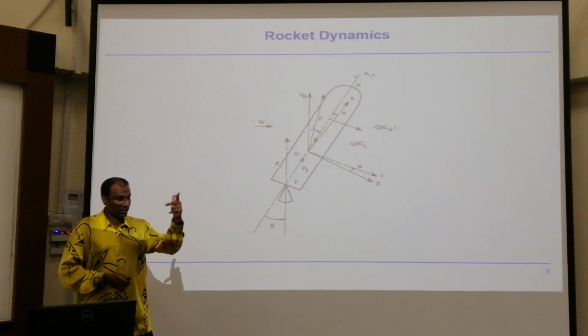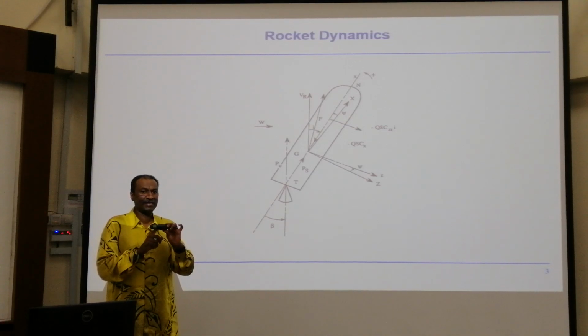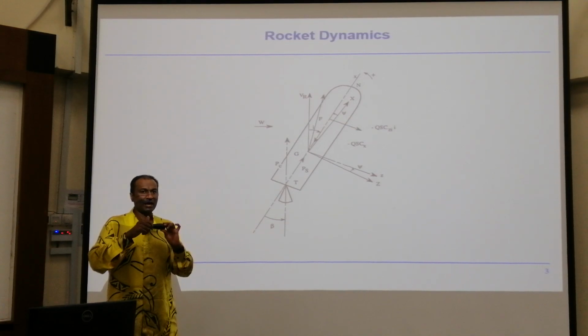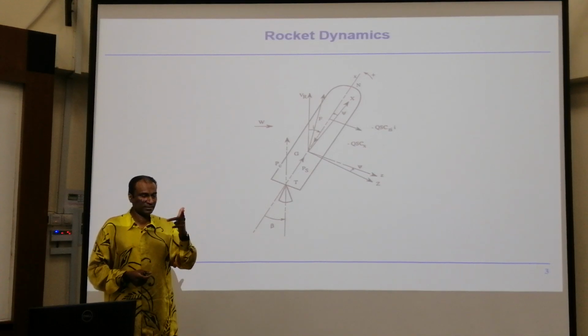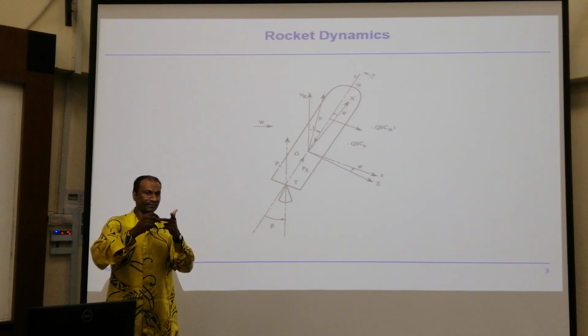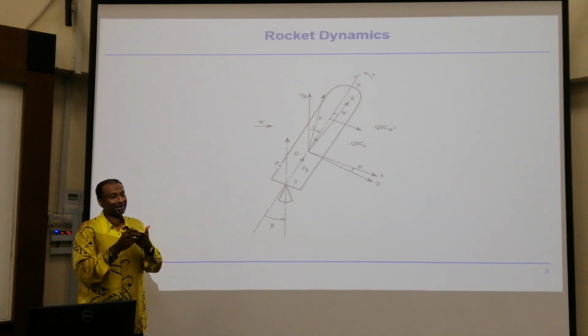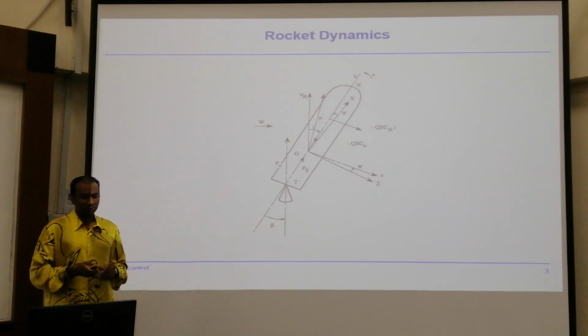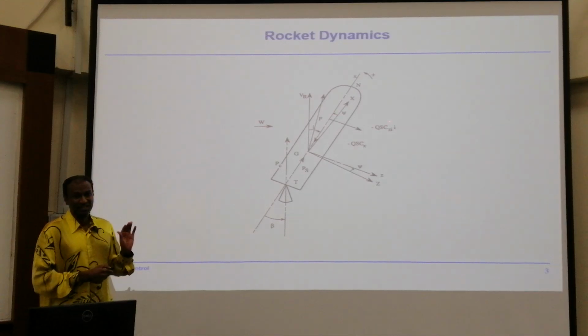As I've said, if you have 3 axes, you can have this principle: fire equally up, fire equally down. It should rotate. Correct? Same force should rotate. So likewise, 3 axes, you want to rotate here, it's easy. Fire up, fire down, fire up, fire down, fire up. So they will rotate to correct the attitude. So that portion is attitude control, which we are not going to discuss too much.